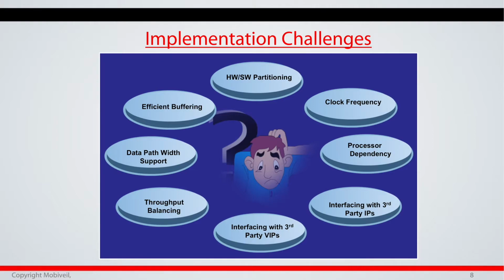And then you have implementation challenges. Those were more like specification related. Here, the implementation challenges is, of course, one needs to decide what goes in hardware, what goes in software. So there are some solutions where even the FTL, which is what we are doing in SSD, people want to offload some of that function in hardware, whether that is possible or not. We have to look at the buffering, what should be the data path width, is it flexible enough to get into FPGA, the same design, can it go to ASIC or not?